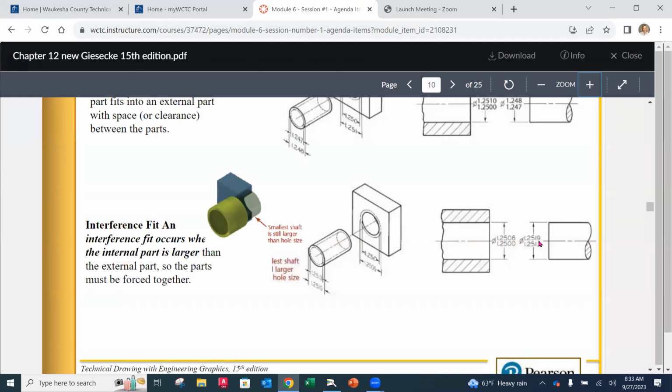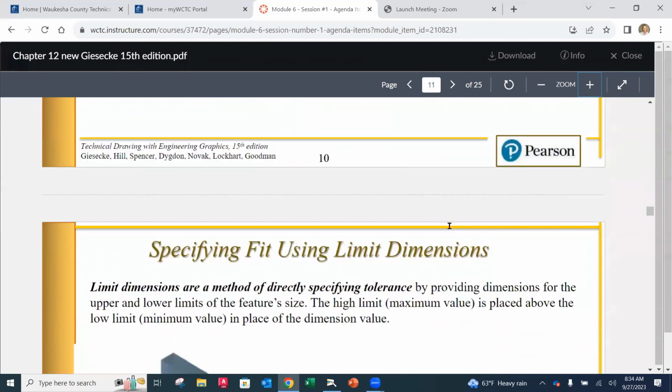Whenever you're in manufacturing, you probably have gotten this in your manufacturing processes class. We talk in thousandths of an inch, right? So we say 5 thousandths, 10 thousandths. In this case, it would be 19 tenths of 1,000th because you're out to that extra decimal place. Okay. So you'll hear that a lot. So yeah, we've got an interference here. So we may have to either pound or press that together.